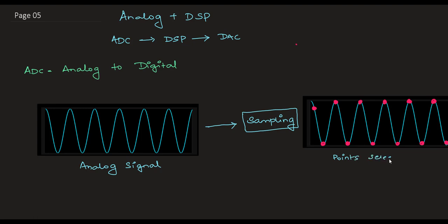If I set it as 6 samples in one cycle, then my sampling algorithm will select 6 points. If I put it as 10, then it will select 10. It will just do what I say. So the setting is just at the top of the program. As we will be seeing, we just have to give the number of sample points in one cycle, and that is how it will be selected.